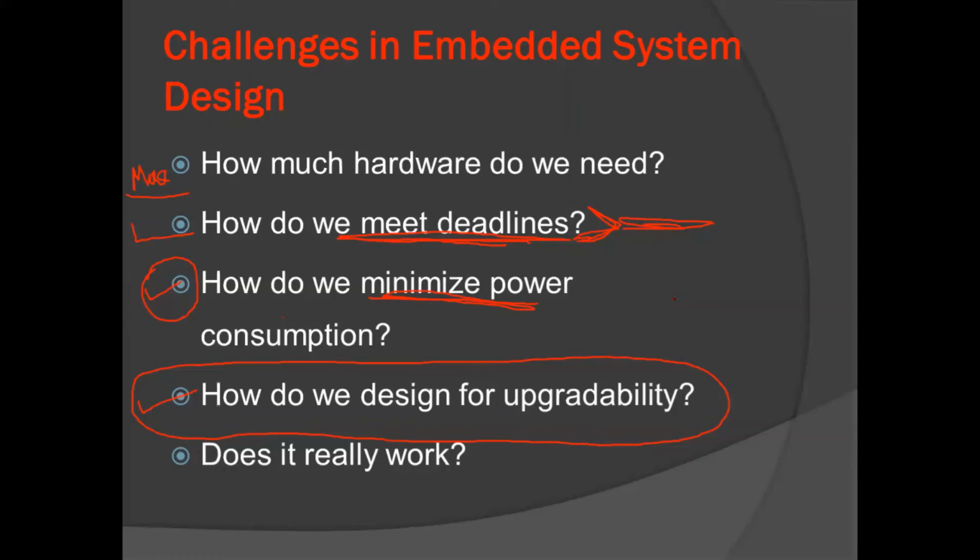And that power loss is considered as power dissipation. So if we are increasing the clock frequency, the circuit inside the chip is going to do more switching, because it is based on the clock cycles, so it will consume more power. So we have to also consider the deadlines and the power consumption. There is a trade-off, right?